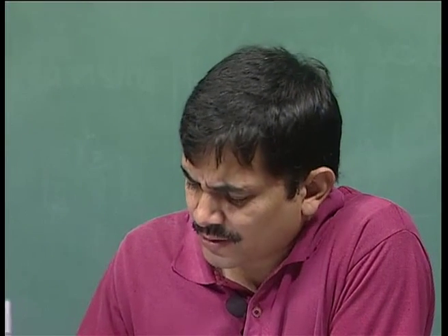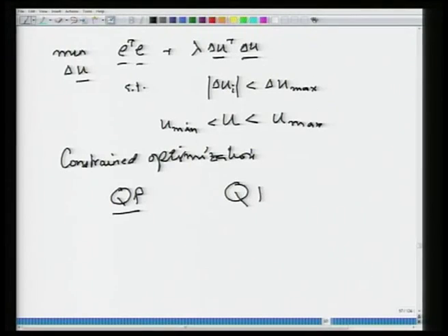Okay, and this is referred to as QDMC, quadratic dynamic matrix control, and one of the solvers that I know of and use quite often is quadprog in MATLAB. This function, this subroutine, does solve quadratic programming problems. Okay. So, quadprog in MATLAB is typically invoked.